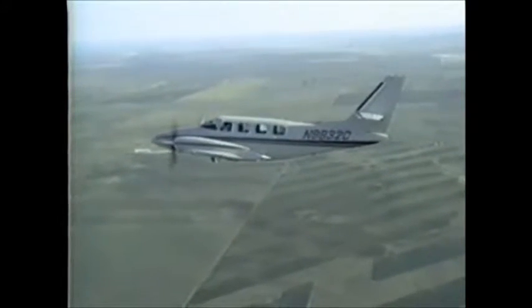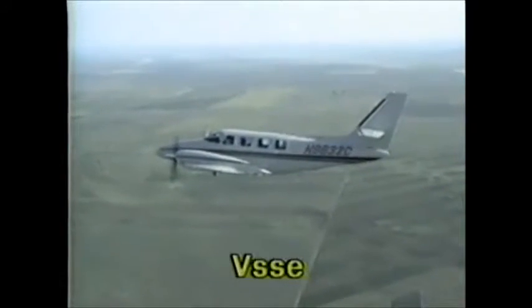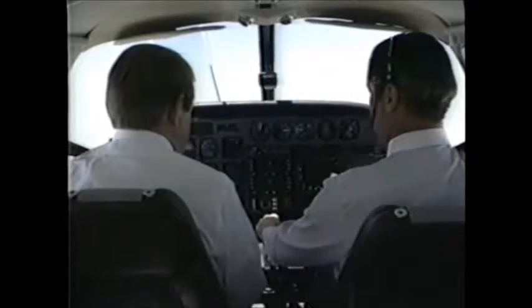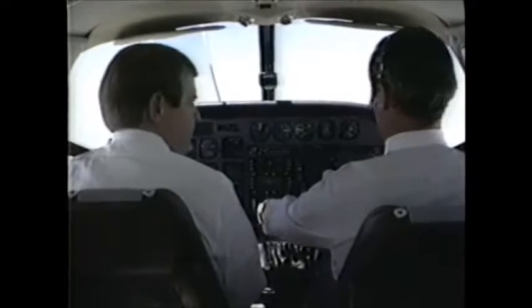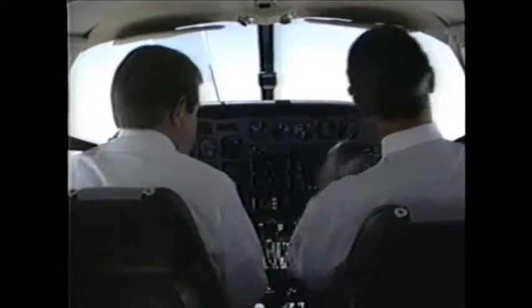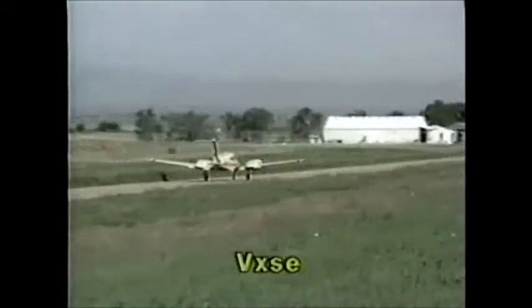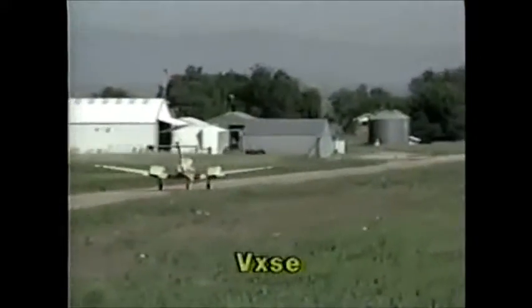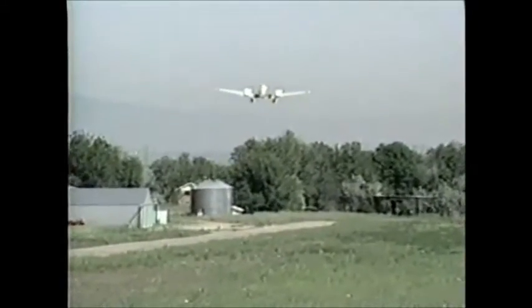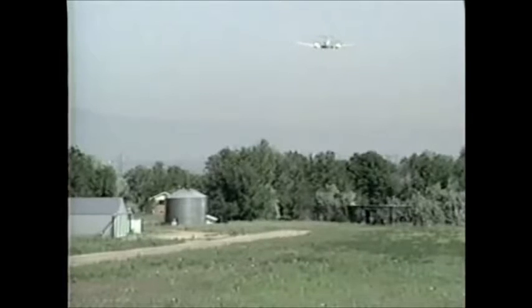An airspeed you will probably use in your training is VSSE, or the intentional one-engine inoperative speed. This is a minimum airspeed established by manufacturers for intentionally rendering one engine inoperative during training. When you practice single-engine airwork, you should never feather a propeller below 3,000 feet AGL. As we mentioned before, VXSE is the best single-engine angle of climb airspeed. This is an important speed during a maximum performance takeoff over an obstacle. If an engine fails after you're airborne, you use this airspeed to clear the obstacle.